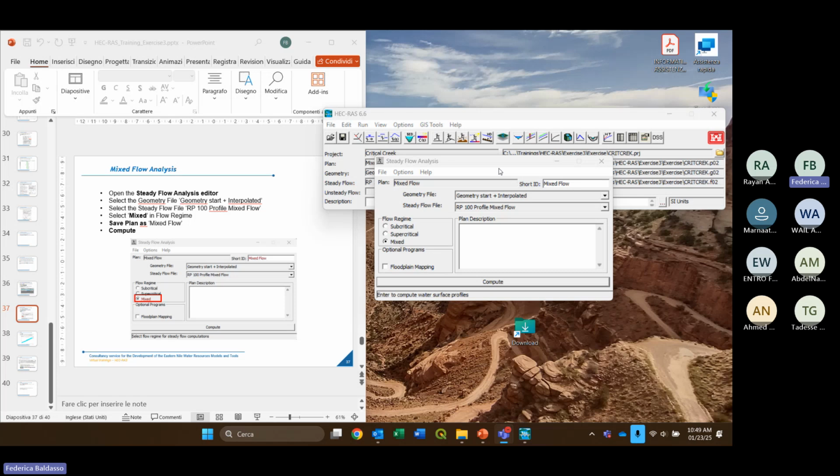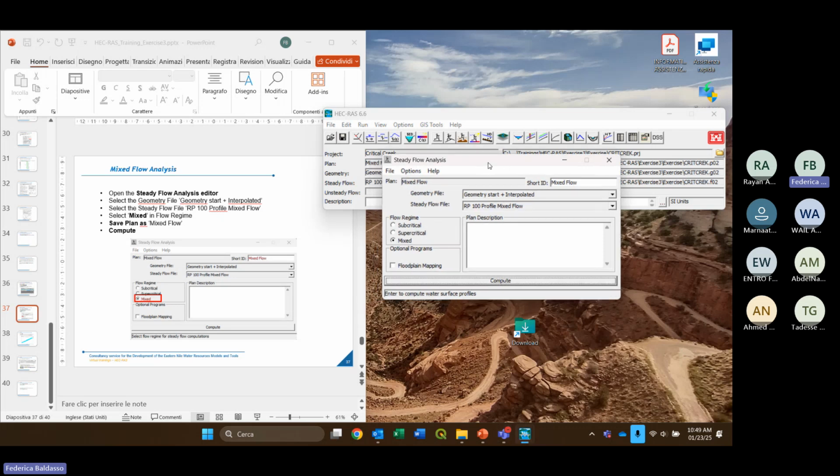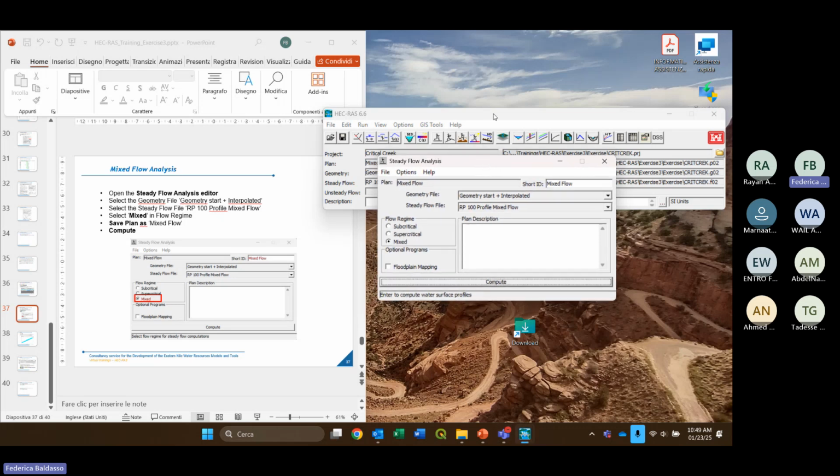We just make sure that the profile of the interpolated cross section were coherent from the upstream and the downstream one, but we do not set any levee or ineffective flow area, so it is correct to have water still divided into two portions.